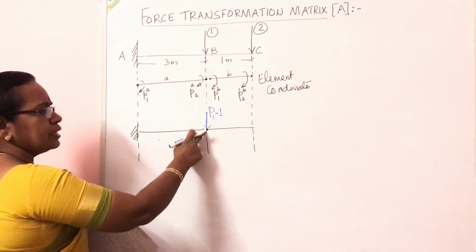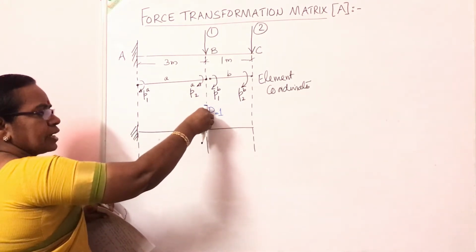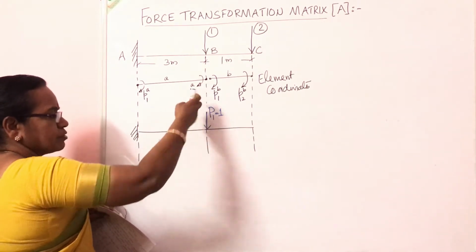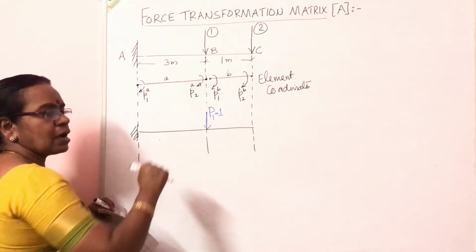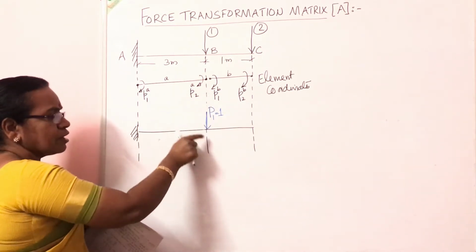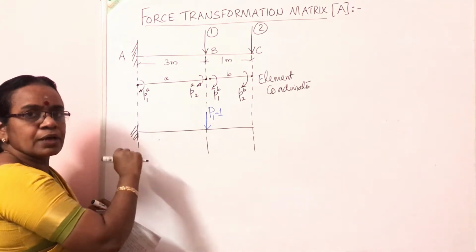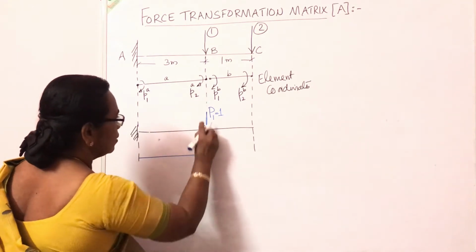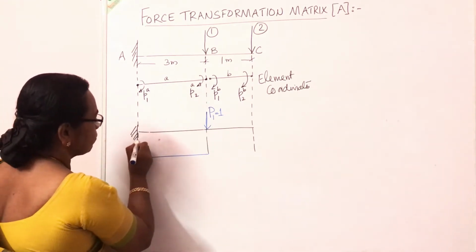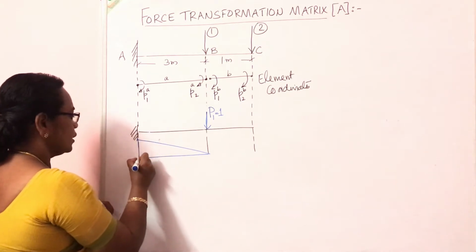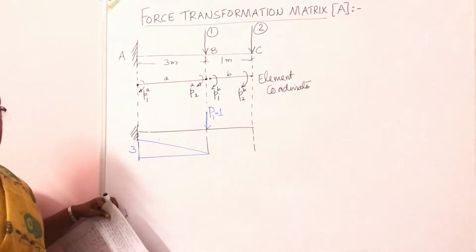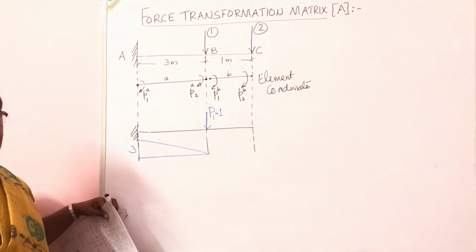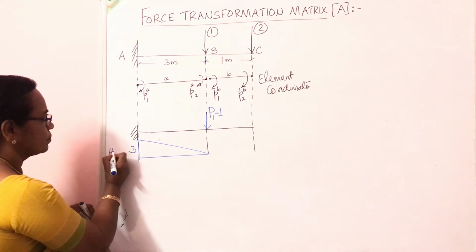So the easiest way is to draw the bending moment diagram. When I give the unit load here, you can see with this pen, in the direction of the load, take moment about this. So this rotates, or the thumb placed like this rotates, in the upward direction. Now this bending moment produces a hogging moment. Hogging moment I will draw above the line. So the bending moment diagram for this case is 1 into this distance 3, that is 3. This is the bending moment diagram, and this is a hogging moment diagram. This tends to bend the beam up. I'll write here it is hogging.